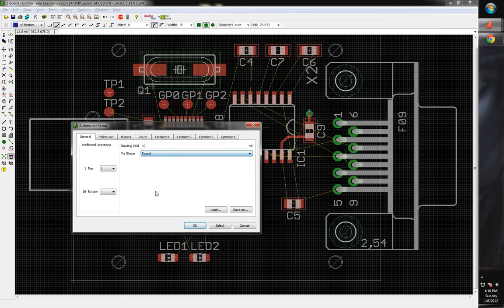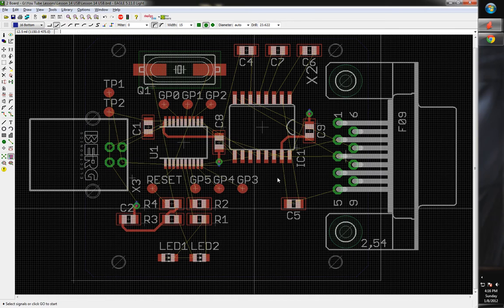And sometimes this helps when, let's say, you need to just maybe auto route a couple, 3 things here and there, or specific things you want auto routed. You can choose select. Like for example, let's select this one. I want that one, and let's say this one, and that one, and that one, and that one. Okay, so you just click on each error wire to select them, and then you hit this go button, basically the little stoplight here. There's stop, and then stop is just cancel. It'll cancel it, and then go. If you click it, it does it.